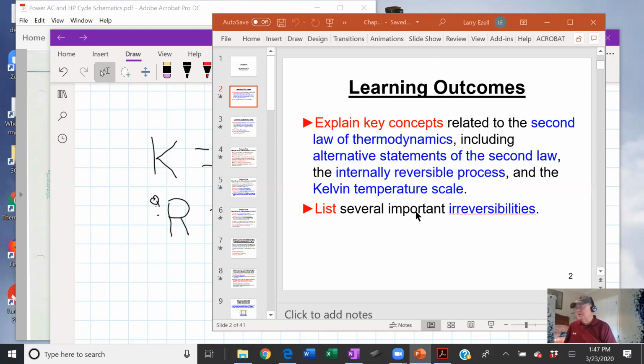But in an internal combustion engine, like I mentioned before, you're compressing the gas or the air, which is 95 to 98% air and 2% fuel. And as you know from being a good thermo student, anytime you compress it to get a higher pressure, you get a higher temperature as a side effect.